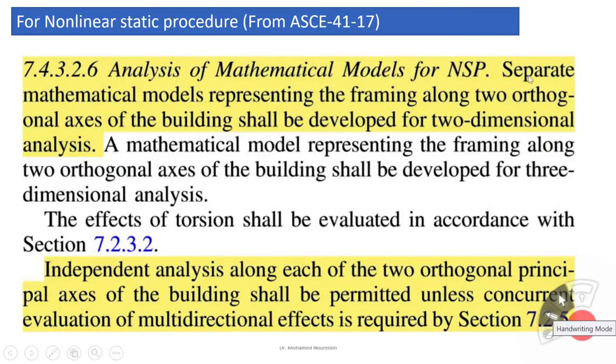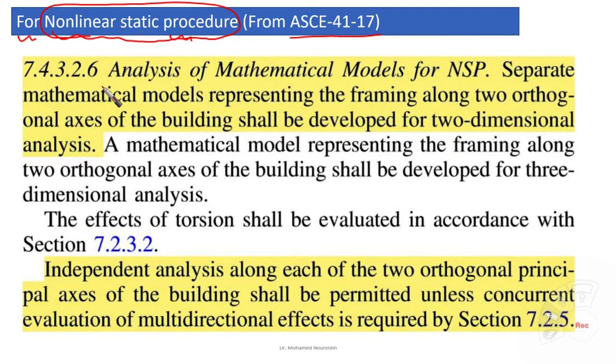Okay, in this video I'm going to talk about the cases for nonlinear static procedure related to 2D modeling, whether it is allowed or not, as I said, according to ASCE 41. Here under the section we're talking about nonlinear static procedure, which is related to pushover analysis, for example, if you are going to use it.